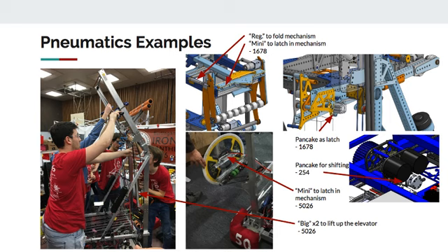In some cases, parts of the pneumatic system used to be like 2 or 3 times heavier than they are now. So I think it was probably more common in the past for teams to make a conscious decision not to use them. But lately, it's been really useful for small tasks. Even this year, a good example was 5499 at CVR. They had no pneumatics in the robot, and it was a conscious choice to reduce the number of parts. So they had no shifting. Everything was motor based, but the rest of the system was rock solid. It just meant there were some things they couldn't do. You can do shifting with servos, but it's not worth it.